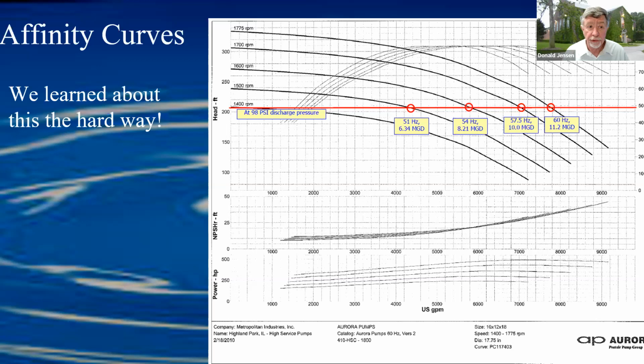So that was kind of a hard lesson, but happily there was no damage to the pump, and we've since instituted in the SCADA a warning to the operators in case they accidentally back into that situation, based on the pump speed and current. It'll give them a warning.